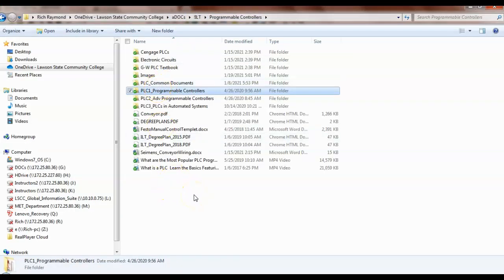So 90% we call in motor controls, we call them control relays. So normally in a control circuit, we have two sections. We have a control circuit, and then we have a power circuit. 90% of the relays don't do anything with power. All they're in there for is to make decisions, right? But eventually we're going to get, huh?